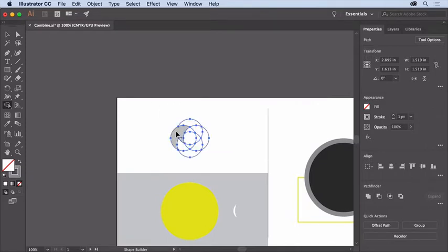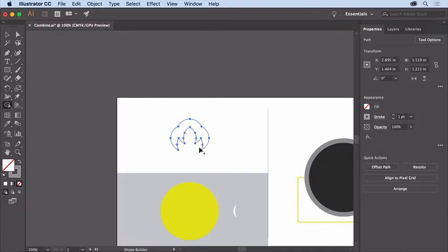Now let's finish the rest. So drag from this newly combined shape to the remaining shapes you see here. When you release the mouse, the shapes are combined. To remove the rest of these shapes, you can press the Option key on Mac OS or the Alt key on Windows, and when you see a minus sign on the pointer, drag through the remaining shapes. Release the mouse button, and then the key. You now have a single shape for the logo.